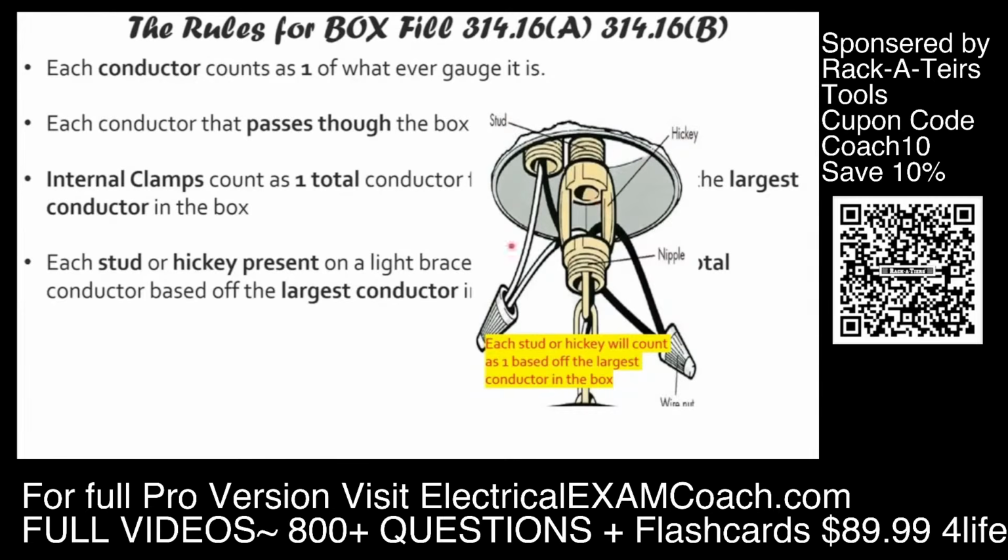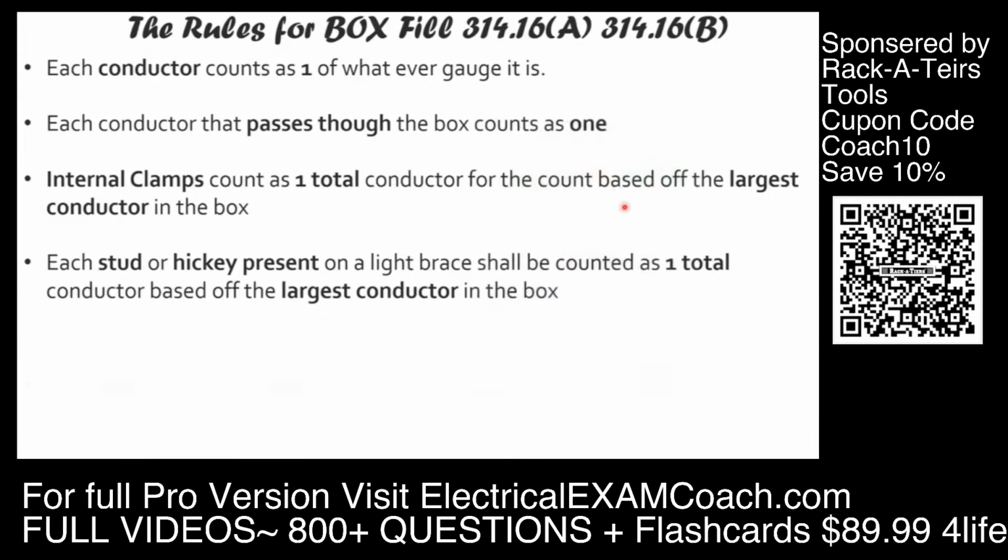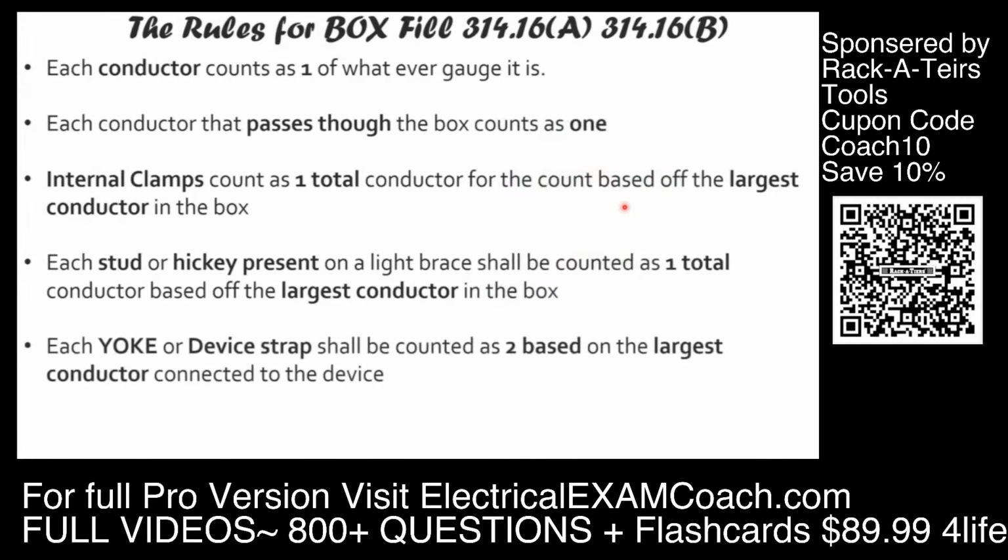In this scenario, in this picture, the stud would count as one of whatever gauge was in the box that was the largest, and the hickey would count as one of whatever gauge was in the box that is the largest. And we're going to do lots of practice, so don't worry about it. Now we need to account for device straps and yokes. What the code states is that each device strap or yoke is counted as 2 based off the largest conductor that's connected to the device.